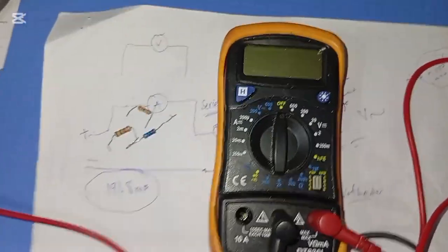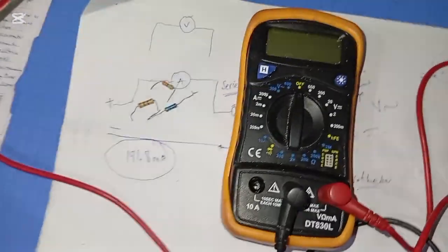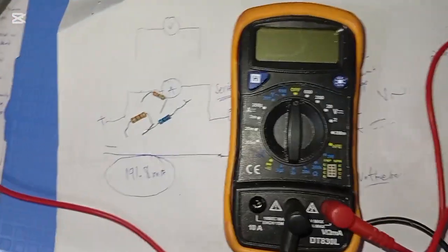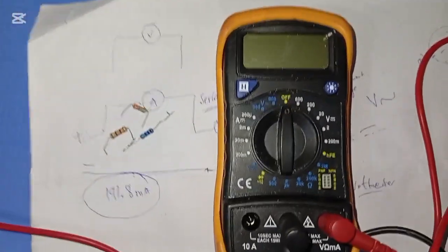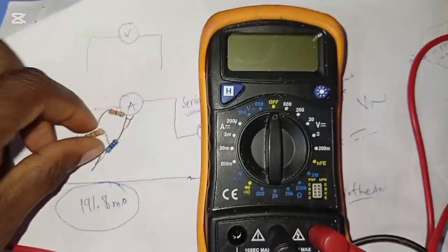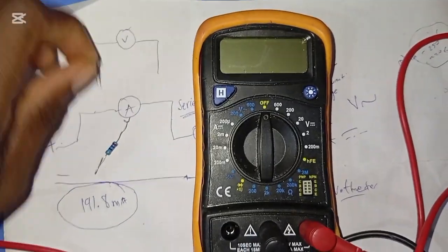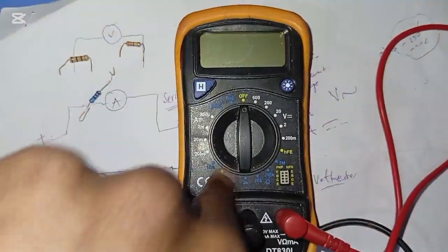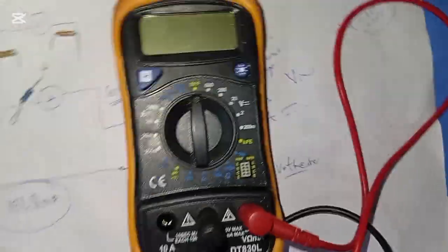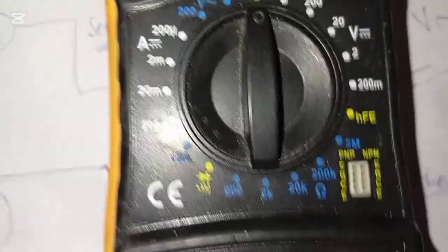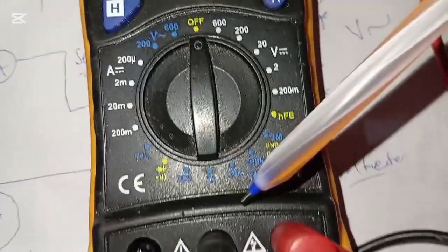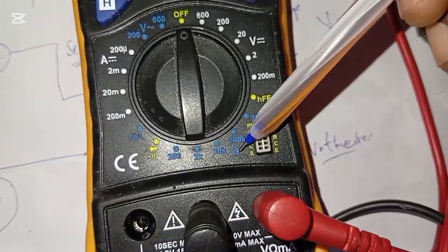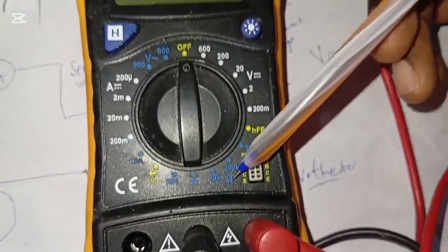There are several ways you can use to determine the value of a resistor, but for today we chose a multimeter. Okay? So we are going to know the value of each resistance here. We'll have to use this multimeter to measure that. You will come to the measuring scale on your multimeter. You will have to check omega. Omega is here. This is the SI unit of resistance.